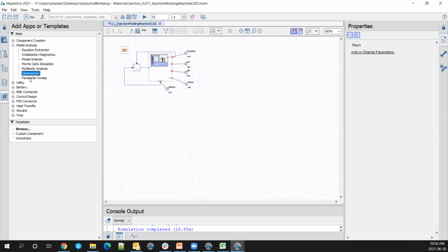Optimization is one example. The other one, which I think a lot of customers involved in the automation industry would use, is to test their controller logic against this plant model. Once you have your plant model set up, ready to go with all the components and nuances that you wanted to design, you can export this plant model as an FMU, which is a functional mockup unit. You convert this model to an FMU, and then you can put it in any automation tool out there that is able to import the FMU and test your controller logic against this virtual plant model. And that's what we call virtual commissioning.